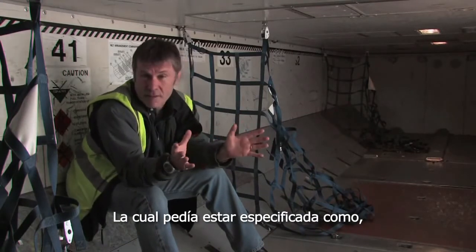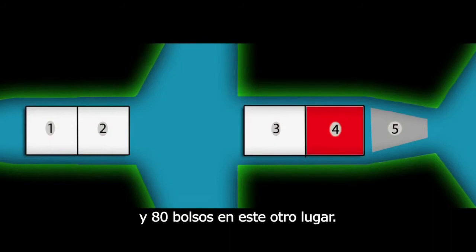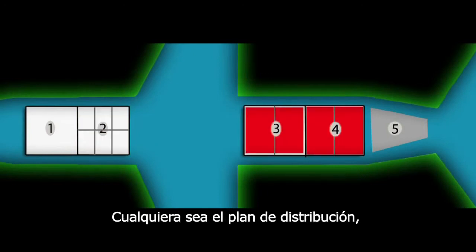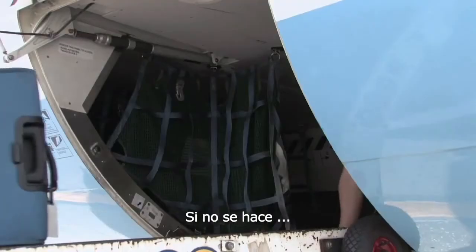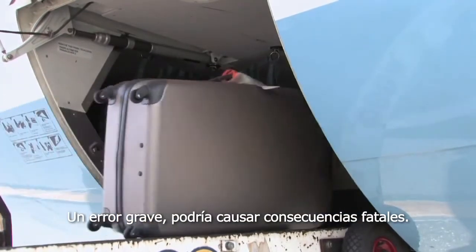Now, it could be specified as 100 bags in here and 80 bags in there, or even baggage containers in the front, cargo pallets in the rear. Whatever the planned distribution is, the aircraft must be loaded in accordance with that plan. If it isn't, a gross error may have fatal consequences.